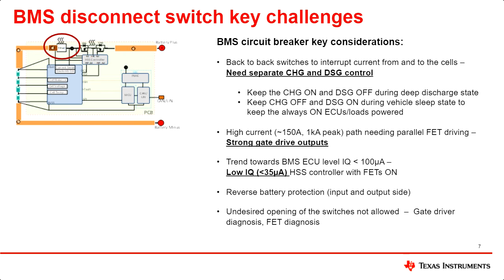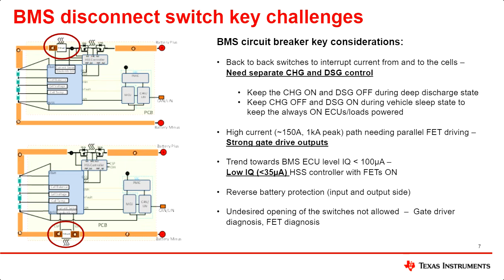Another key point here is that since this controller is sitting close to the battery and is going to be always on, the IQ of the controller itself has to be pretty low, especially when the FETs are on. Some other important features required here is that the controller needs to have reverse polarity protection as well.